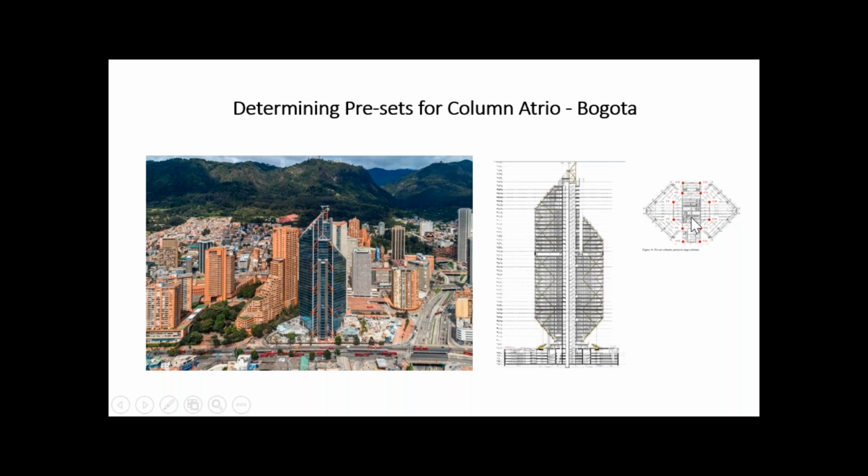This is the central core, and what you have is 2 diamond-shaped floor plates, and you have perimeter combination concrete and steel columns that are supporting the floors. So you see that the loading has to be tied so that we can ensure that the movements between the support off of the core and off of the columns and the steel and whatever else, we're going to get equivalency, so the floors don't end up being sloped as we get further up.